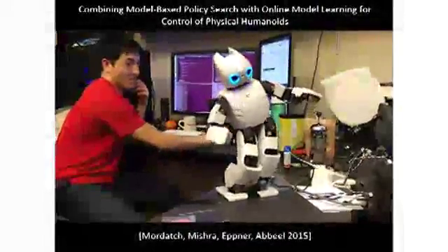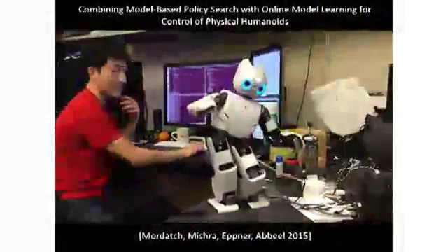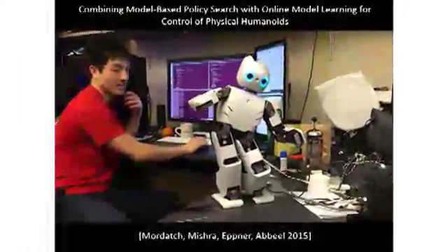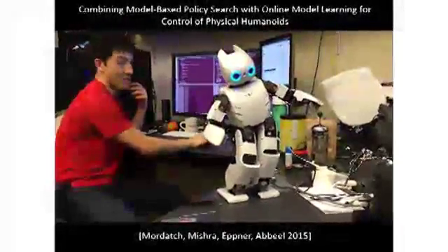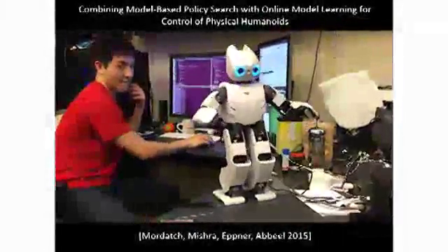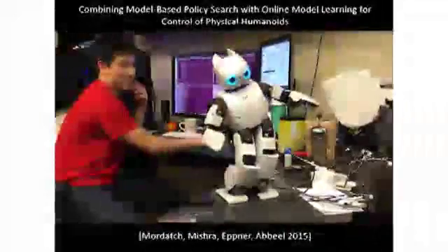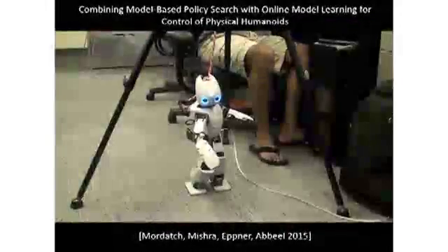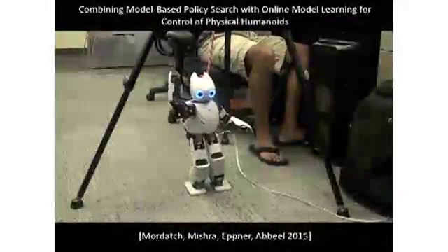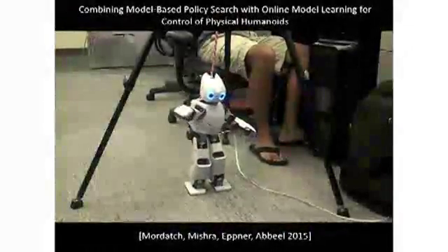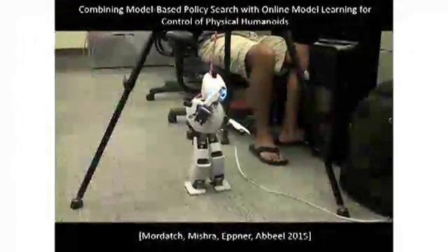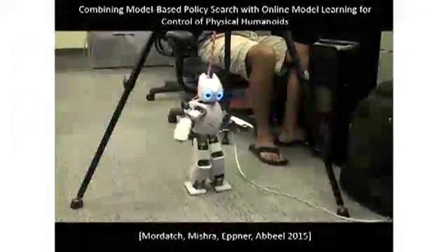And here, the goal is to get the torso to a particular orientation that is controlled by my co-author's mouse cursor. And we're not making use of, say, end effector or Jacobian transpose control or any of those ideas. This is learned just coming out automatically. And here the goal is to, for example, move the end effector of the hand to a particular location that is, once again, controlled interactively by the cursor.